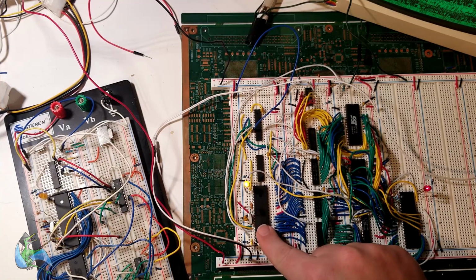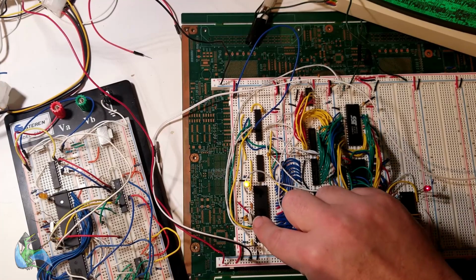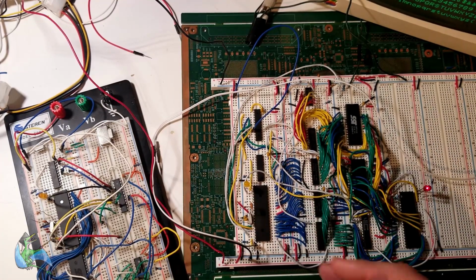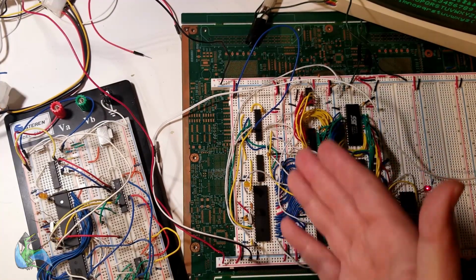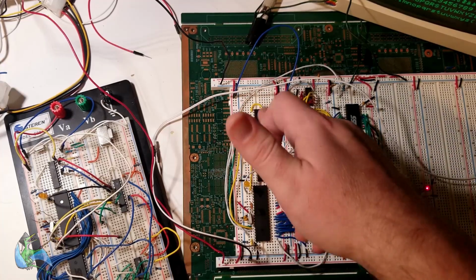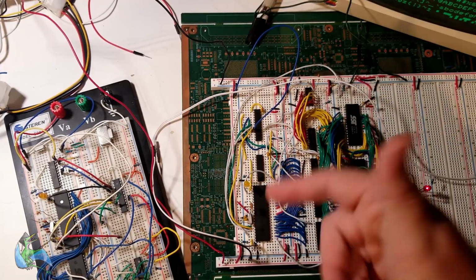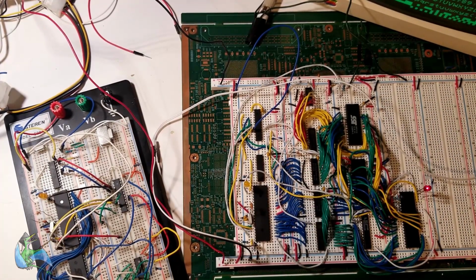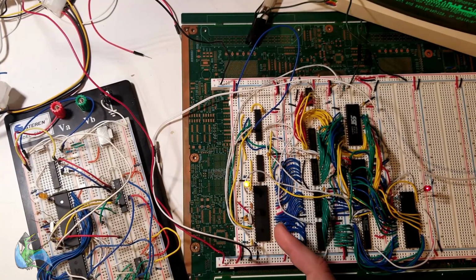It's not generating the clock with software. These chips have a fuse setting that allows the clock they generate with their crystal to come out. I don't even need to do that. I could use an external clock and just feed it to both devices, but this is a way to get it for free.